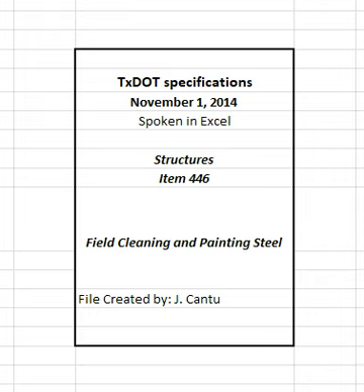Keep paint pots no more than 20 feet above or below the level of spray application of paint during painting operations. Do not allow fluid hoses to sag more than 10 feet below the level of the bottom of the paint pot or actual spraying operations, whichever is the lowest point. Keep hoses serviceable with no cracks or deterioration. Equip paint pots, or other containers from which the paint is dispensed, with agitators that operate whenever paint is in the pot.